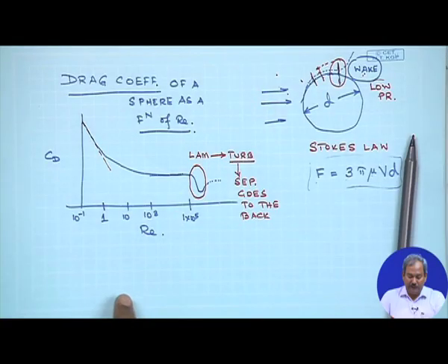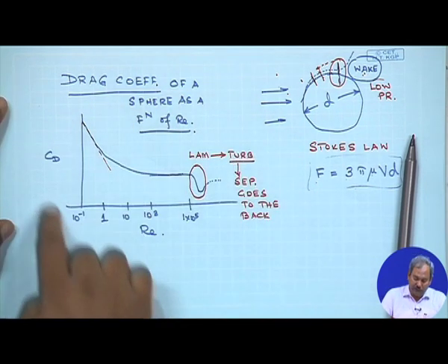This is the reason that a turbulent boundary layer is often preferred over a blunt body. So, for a blunt object, we would rather have turbulent flow than laminar flow in the boundary layer. This figure of drag coefficient CD versus Reynolds number is a very well known figure.